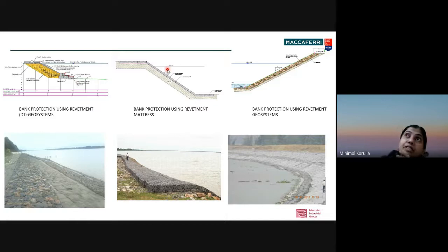If the flowing water carries shingles or soil particles, it can abrade the river bank. So whatever protection we give in the river bank should be strong against abrasion, against the impact of stones hitting, and against the impact of the water velocity. And if it is a seashore, we may have to think about cyclic forces like waves, winds, and all.